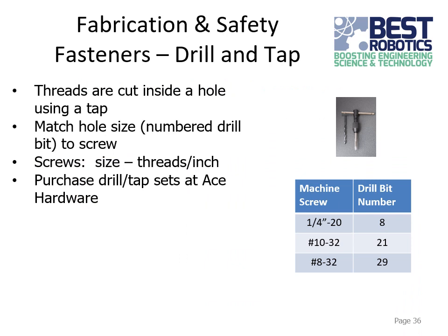So for fasteners, and I'm talking about screws here mostly, a lot of times it makes sense to pre-drill screw holes in your wood and stuff like that, so you don't split it. But if you want to tap a hole, then you have to be particular with getting the right drill size and the right tap to match the screw.